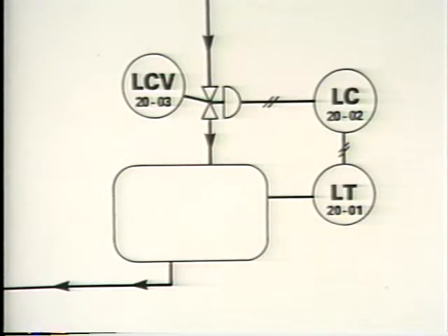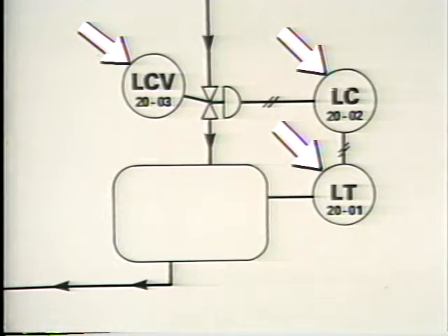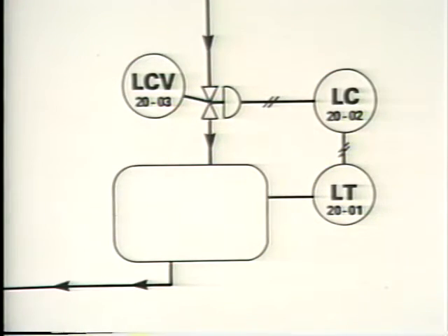In a P&ID, control system instruments are generally identified by circles, and the circles usually contain letters and numbers that identify the instrument and the system it is in. The letters used to identify the instruments are pretty standard, and they usually have specific meanings.